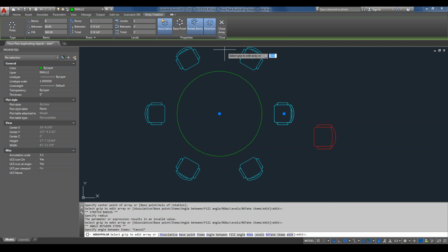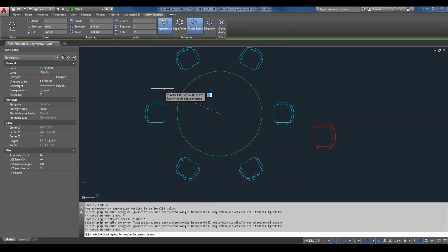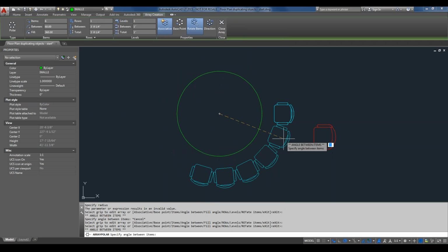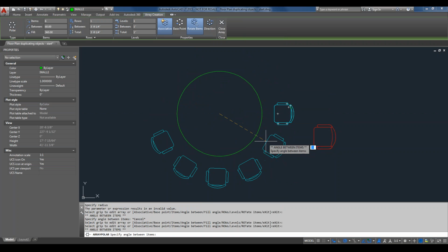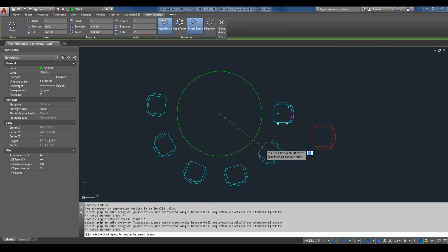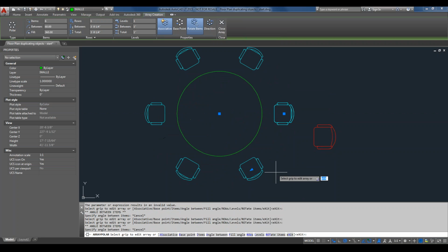We also have a direction function here. The polar array goes counterclockwise by default, and maybe you want to change that to go clockwise. So, whoops, there we go. So, oh, I guess they did change the direction on me. It used to go counterclockwise. I may be thinking of the old array command. Actually, I am thinking of that. So nowadays, clockwise, there we go.